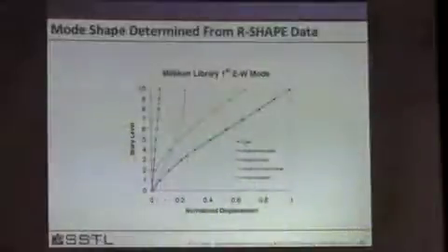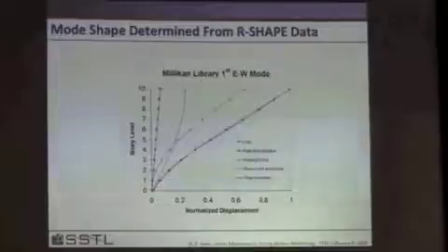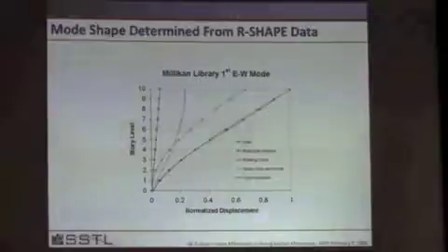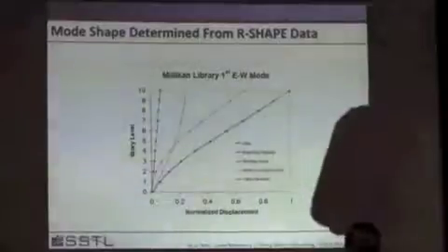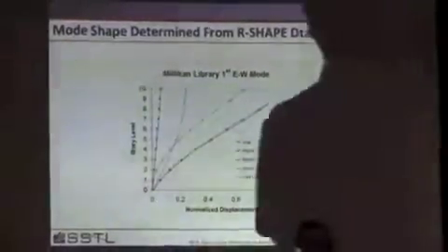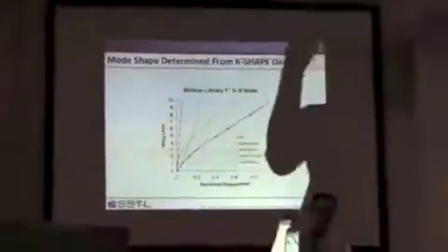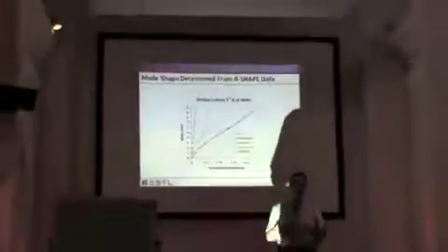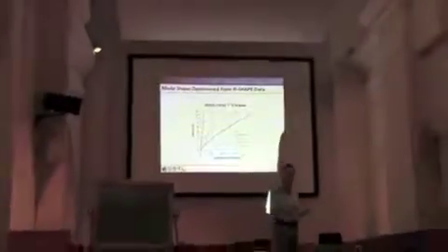Pardon? That's followed in torsion. In this particular case, this is just pure bending. This is the east-west first mode. I'm sorry? The rigid body motion. The rigid body motion was just, if I'm here, it's just rocking on its foundation. So it's a pure rocking behavior. So there certainly could be torsion, but this is a rectangular building, and so there's no noticeable torsion there.